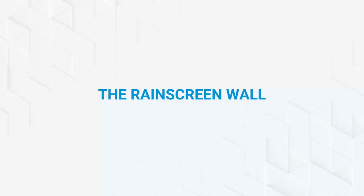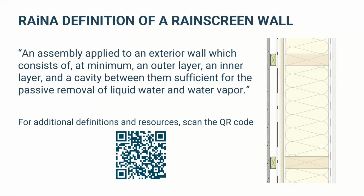Rainscreen wall. So what is it? This is the definition that a bunch of industry experts came up with: an assembly applied to an exterior wall which consists of, at minimum, an outer layer, an inner layer, and a cavity between them sufficient for the passive removal of liquid water and water vapor. So what does that mean? Also, there's a QR code. If you want to go there, it's going to take you to RAiNA's website. We've got lots of other defined terms and resources, which I'll talk a bit about later.